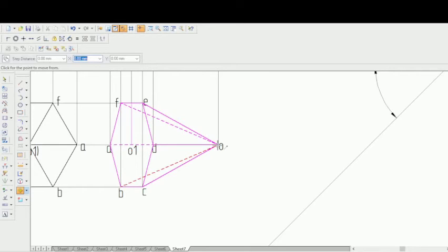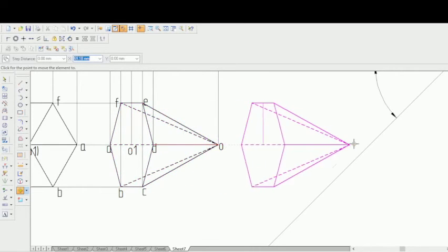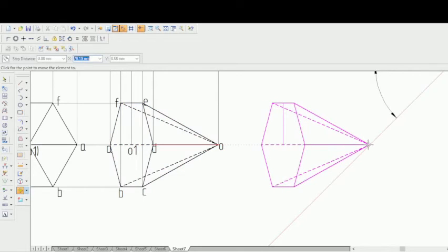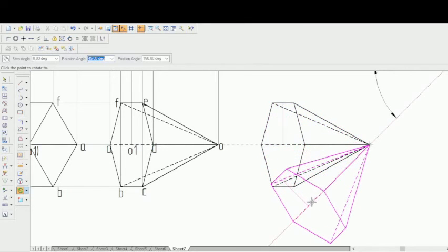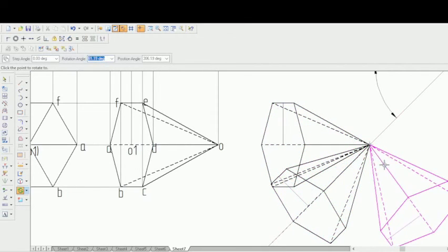So now let me move from this O corner and place it over here. Now let me use the rotate option, so that copy is switched on. Let me select this completely. Let me select this corner and this opposite corner, and rotate like this.